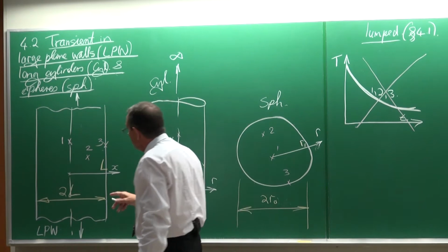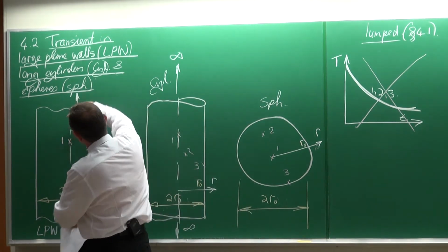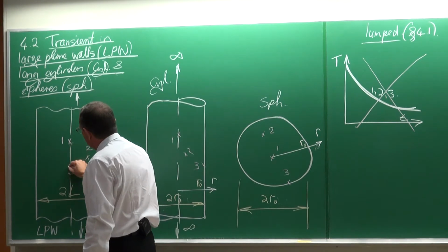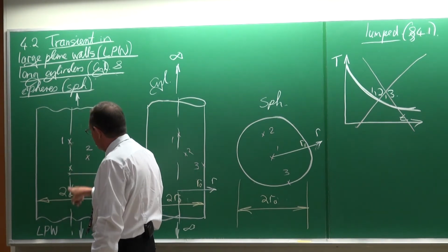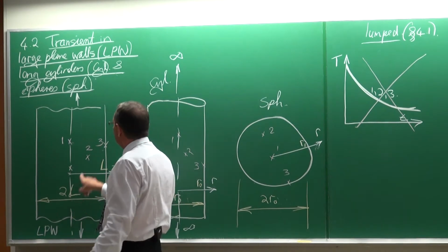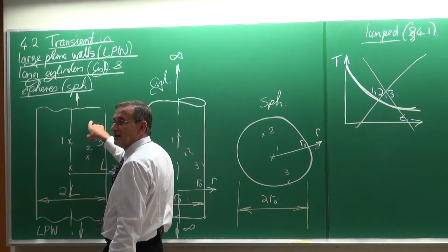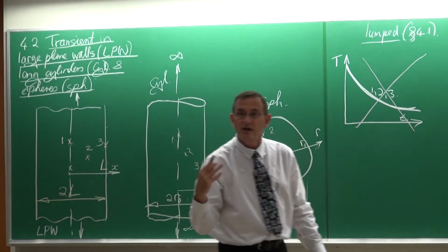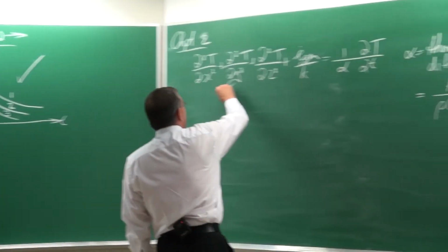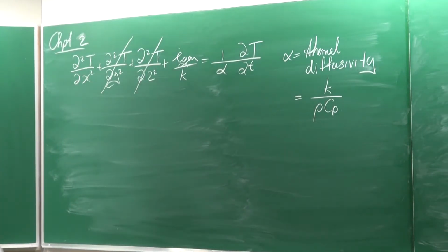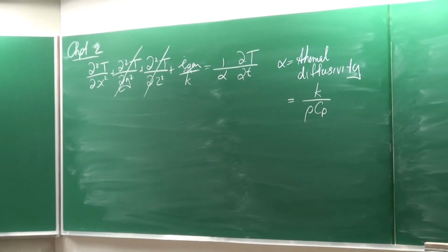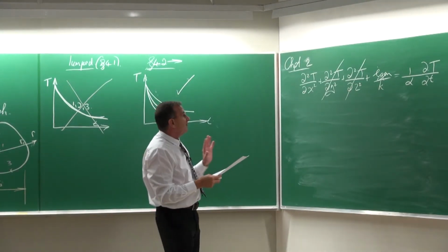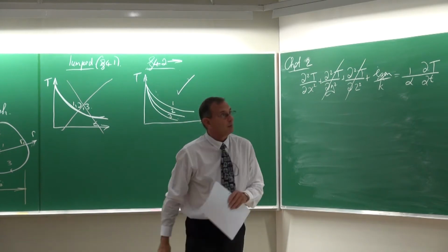It would therefore mean that if you've got the temperature at the center at this point, then it would also be the temperature at the center there, and also there. This temperature would be the same as there, there, and there, and the same there. So therefore the heat transfer rate is in 1 dimension only. For that reason, we are not going to consider those 2 terms, and that is then the general heat conduction equation, which is now valid for this problem.